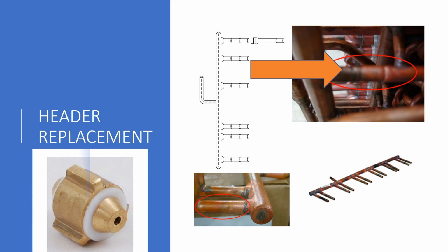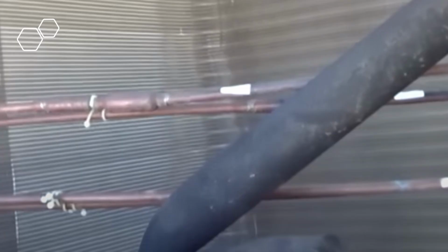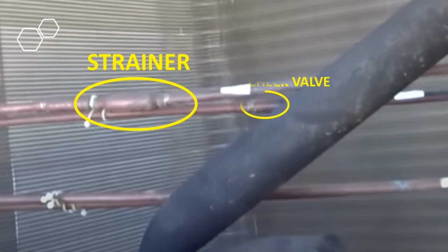Unlike residential pistons that move back and forth between heating and cooling mode, these pistons are impressed into the tubing and are stationary and do not move. Because these pistons are stationary and do not move, also in the refrigerant line there are check valves and strainers to direct the flow of refrigerant between the cooling mode and the heating mode.